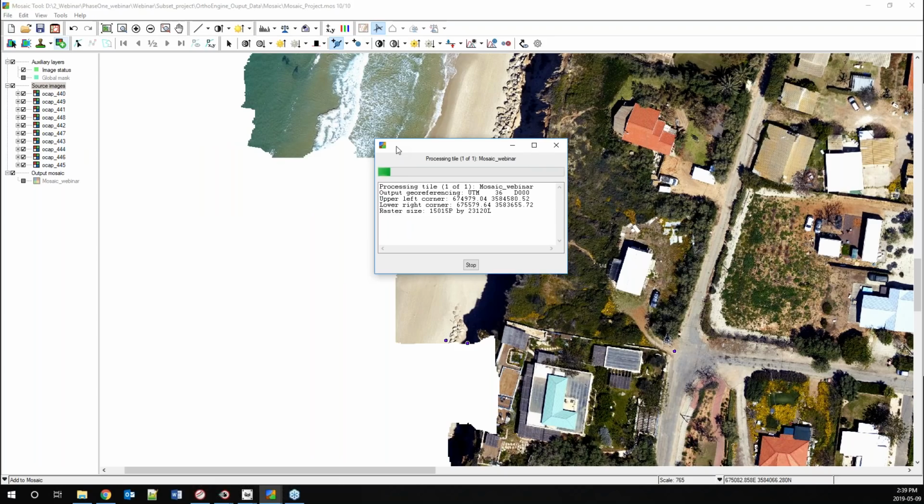So in this workflow, unlike other workflows where we would not have identified problems like in the bridge until we've generated the orthos, we can actually avoid that by fixing them in the DEM and seeing their fixes in the live ortho preview, so that when we get to this mosaic step, we won't encounter situations like that. However, we do have a number of post-mosaic editing tools, but I will explore that in my next demonstration.